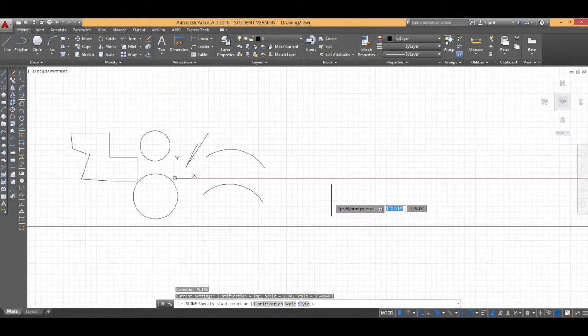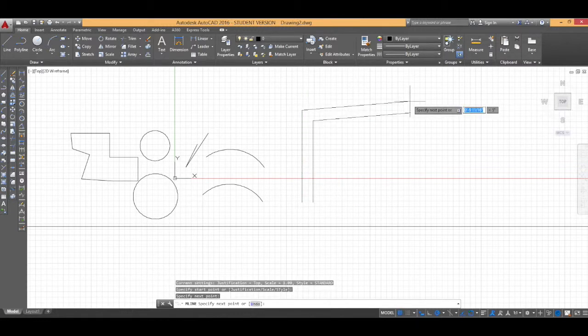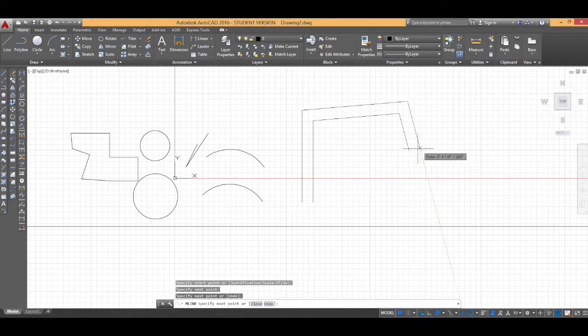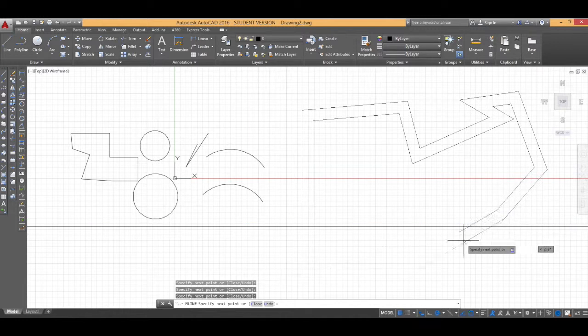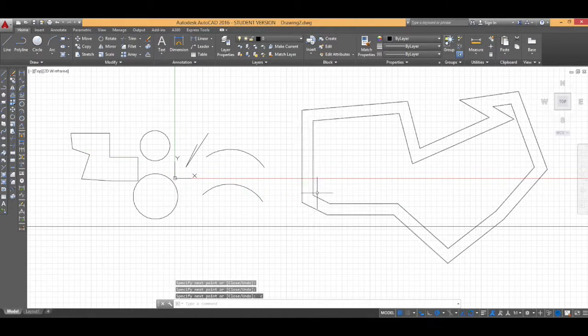Finally, M-line creates multiple lines simultaneously. Play around with this tool by simply clicking and dragging. You'll notice that as we drag and move, the interior of these lines adjusts to be able to maintain its justification. Again, this will be extremely helpful when we go over making a simple condo. You can type C, much like with polyline, to close off the feature that you've just drawn, and it will match accordingly.